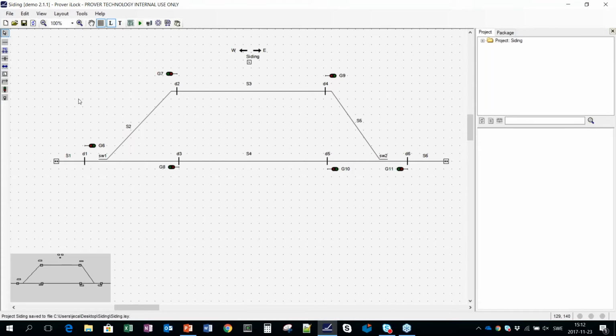For these demo signaling principles, all information needed comes from the track layout. In many concrete projects, there are other types of information that are added by configuration tables. But in this case, the track layout should be a good basis for actually computing the software code for the interlocking.